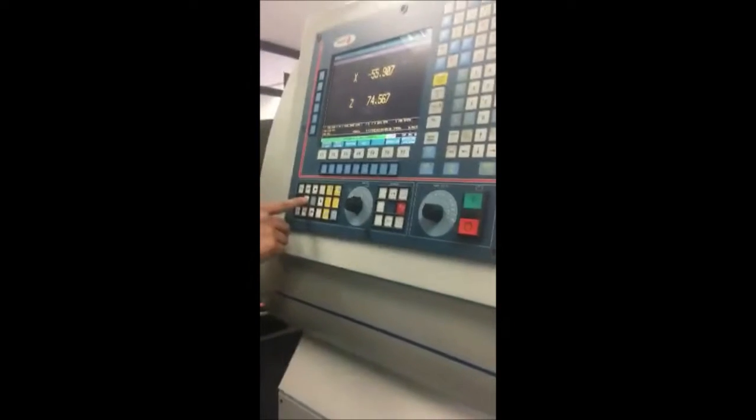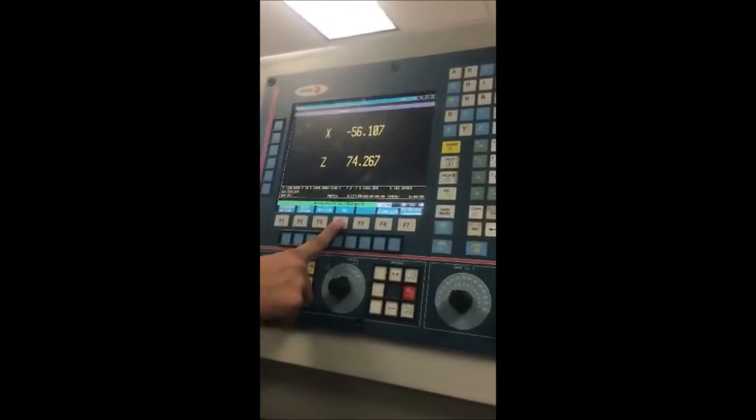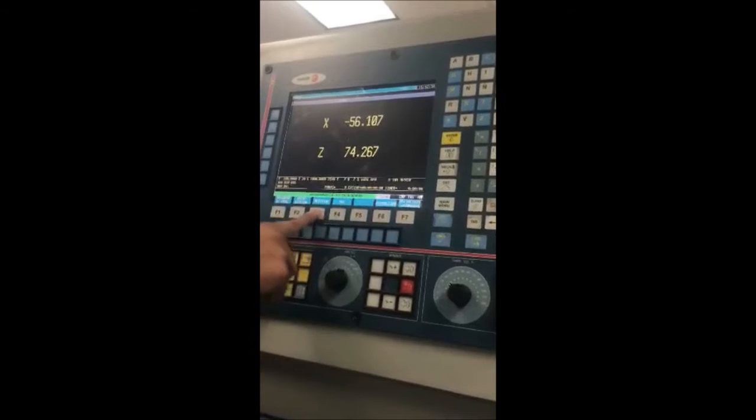Something very important that I forgot to tell is that you must measure your part before anything else, by length and by radius, because those will determine your part 0. Now you have to wait and be pretty careful to touch the cylinder part and to hear that the tool already touched it. After this, you go to Medición, then Z.